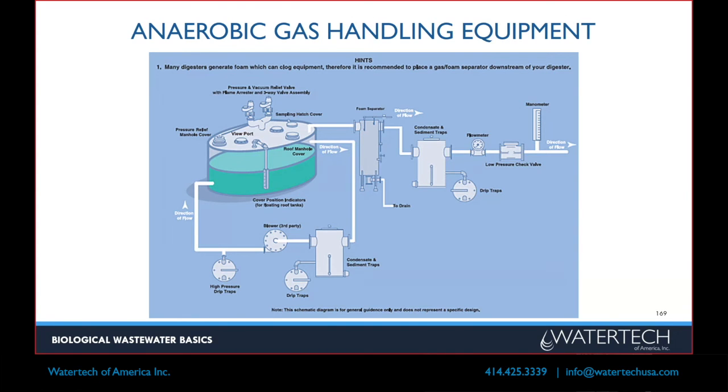This is a side of anaerobic that's critical from a safety standpoint, and that's gas management and gas safety. So it's a flammable gas that you're generating. So you need things like condensate traps, you need flame arresters, flame checks, just all sorts of safety devices. So in case something does spark and there is a fire, that it doesn't cause a problem.